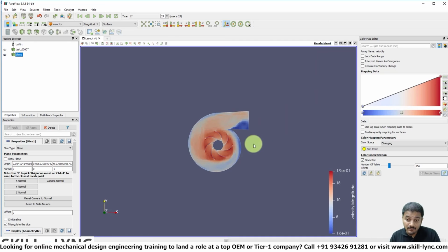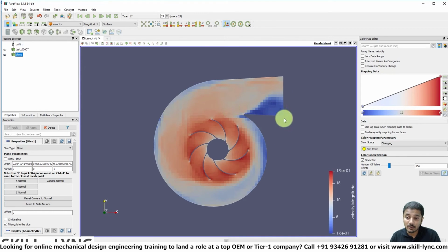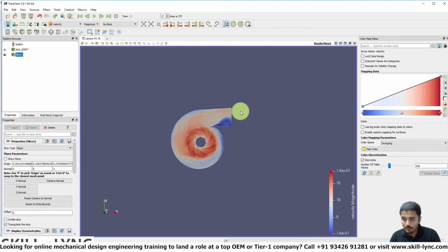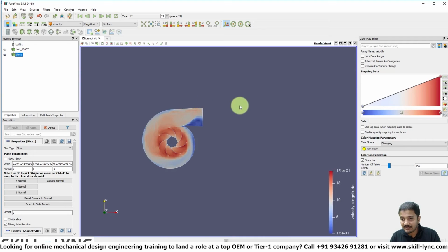Well, to start with, it's a bad idea to place the boundaries so close to a separation bubble. What's going to happen to this particular flow pattern is, if you extend this outlet, then this flow that gets separated is going to reattach, and then you will have smooth flow through the outlet, right? So when you're running a CFD simulation, if you want accurate results, you need to make sure that in the location of the boundary condition, the boundary conditions are actually valid.